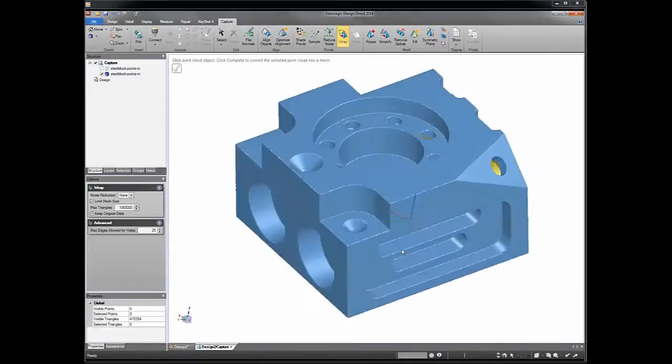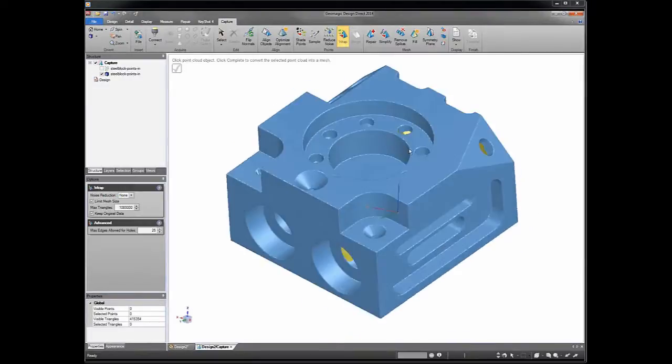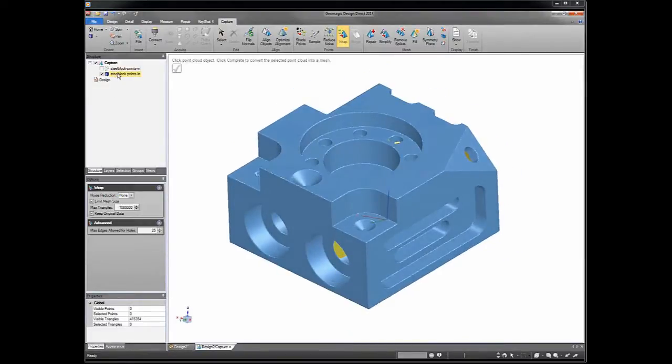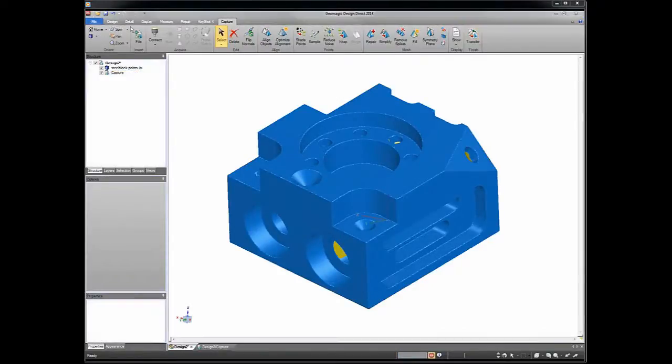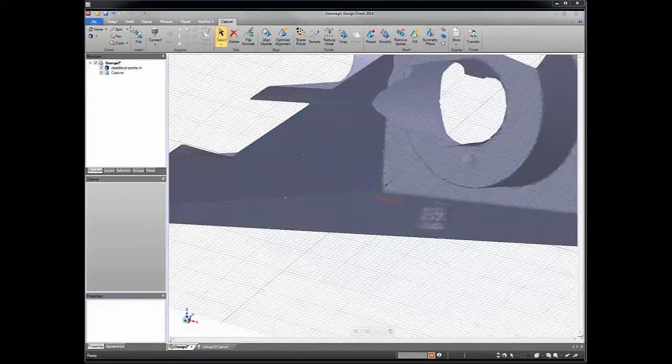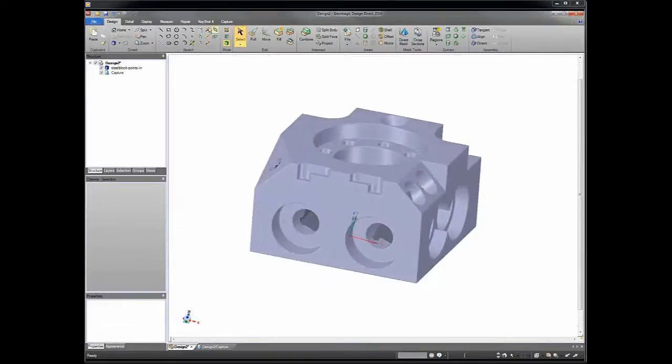We're just going to extract the outer portions that we can see, and we would do the rest later. So one thing we'll do is go ahead now and start the modeling. We click on this object in the tree, and we choose to transfer it within the same application. We're throwing it over the wall so that the SpaceClaim tools are aware of it, and it just changes color. Now we're able to use tools like Pull, Move and Combine to start extracting geometry.